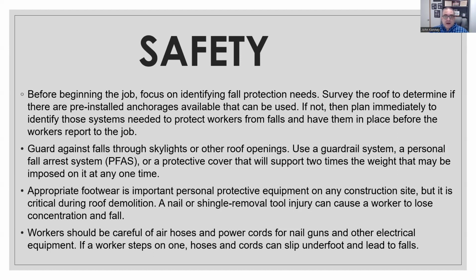Workers should be careful of air hoses, power cords, nail guns, or other electrical equipment. If a worker steps on one, the hoses or cords can slip underfoot and lead to falls. I've even, over my career, seen people fall off roofs by tripping over trip hazards such as an extension cord or other cords. So again, be very careful. Always keep that safety mindset present.